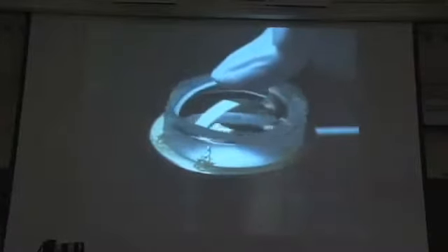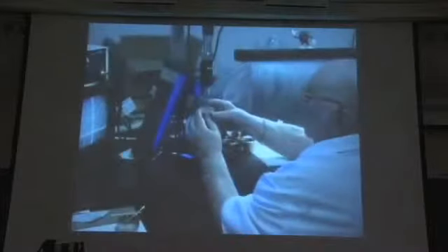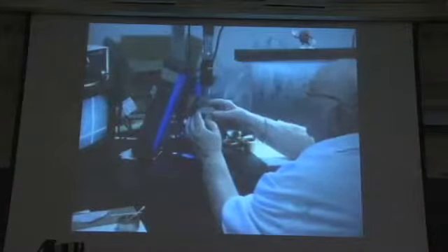She gives the other concave lens a little more scrutiny before she cements it onto the convex lens. She applies pressure to spread the cement between the two lenses. Cementing them together means they'll be less likely to shift around in the lens barrel. She checks for dust one more time. Then it's under the microscope for an optical alignment of this double lens. Because the cement isn't yet dry, he can push the top lens around and adjust its position.